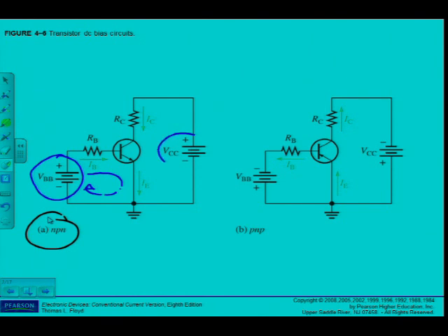I have another supply which is called VCC, which will let the current flow in that direction for IC, and I can see that my base collector junction should now be reverse biased, and I have my forward reverse bias condition as I should have for a biased amplifier circuit. Then the currents, as I can see, IC, IB and IE. And we've also learned that IE is the largest because IE is equal to IC plus IB. And the same applies to the PNP transistor as well.